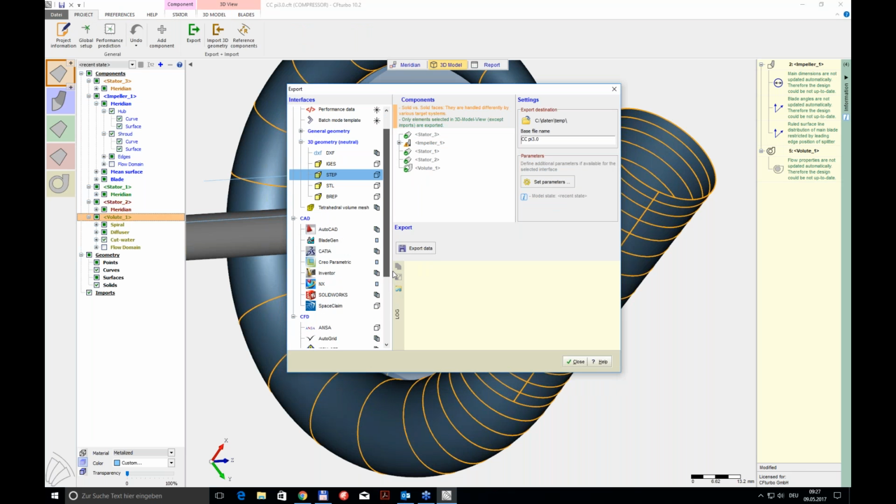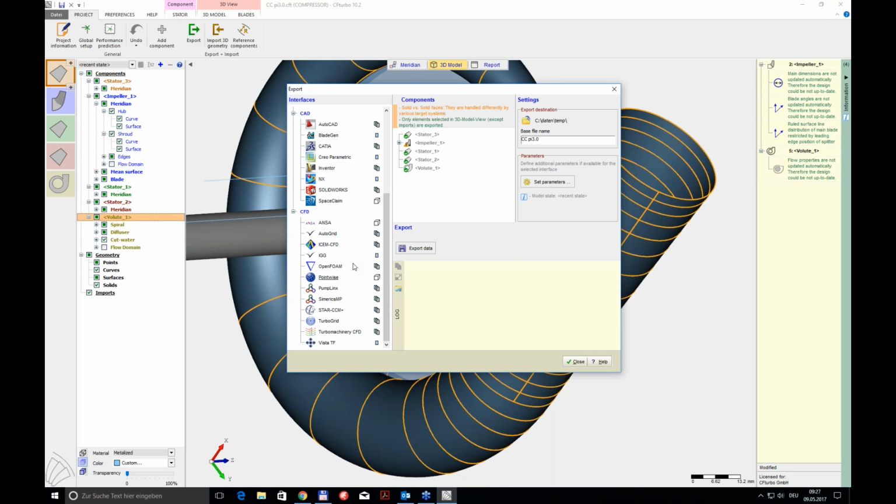But I want to save time, and that's why I just want to show you quickly how to start the validation process. And to this end, one can change from different CFD export interfaces, and the one we look at today is the Turbo Machinery Design CFD interface. One has to get rid of the space in the name, and I also have to have a gap here.